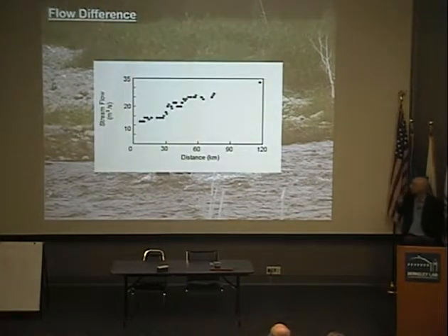That's just some data where we did a large number of flow gaugings on a stream over about 70 or 80 kilometres, and you can see in this case some very significant groundwater inflows due to spring discharge. It's a means for potentially calculating the inflow or outflow rate from the stream.